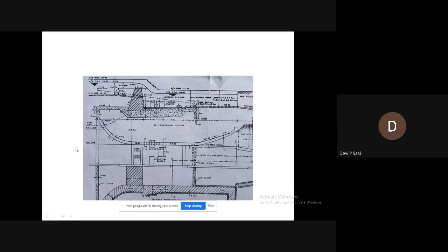Okay. Here you know the discharge is above 14 cumec and we are providing a trapezoidal crest. If the discharge exceeds 14 cumec, the wing walls are curved from the upstream edge. They are similarly curved, but it is given an angle of 60 degrees, as you can see in the picture, and a radius of 5 to 6 times h.